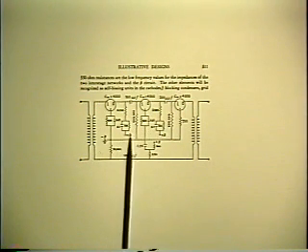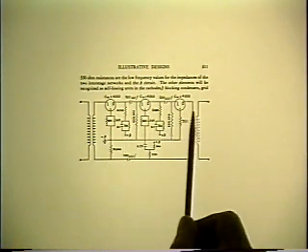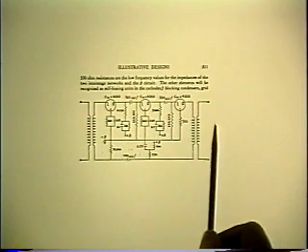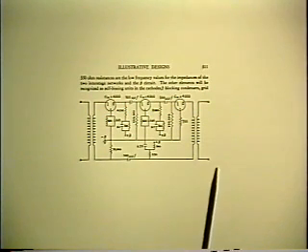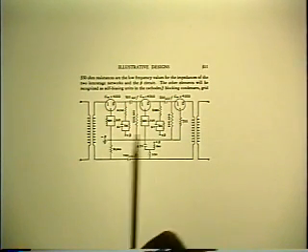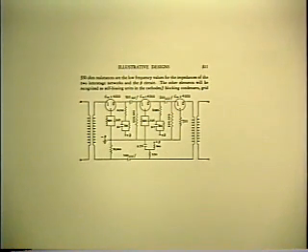And this was fine at the time, but of course we just don't design systems this way anymore. The whole philosophy is different. Because then you wanted to use as few active devices as possible, but you could use all the passive elements you wanted, including magnetics. Now the philosophy is exactly the opposite. You have ICs with gain coming out your ears. And you don't want anything outside the IC. And what you can put inside is R's and C's, and you can't put inside the magnetics, so you don't want to use them. So the whole philosophy is backwards. So the examples are not very helpful.